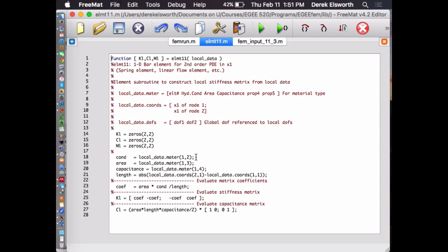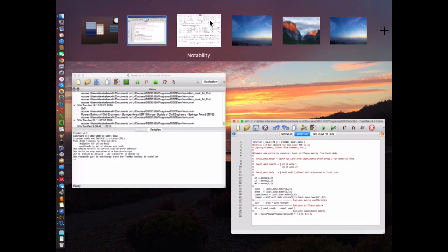Everything's localized. So when you go into the element, you come into the element with no conductance matrix, nor any capacitance matrix, the S matrix, nor any mass matrix. We won't use that in the stuff we're doing. It's for dynamics, but those would be the 3 things. Actually, it might be worthwhile writing out.